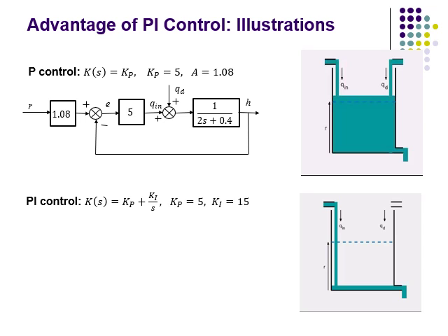So in this case, the steady state error is not due to any problem with the setting of the P control, it's just due to the fact that we've got this extra flow coming into the tank.